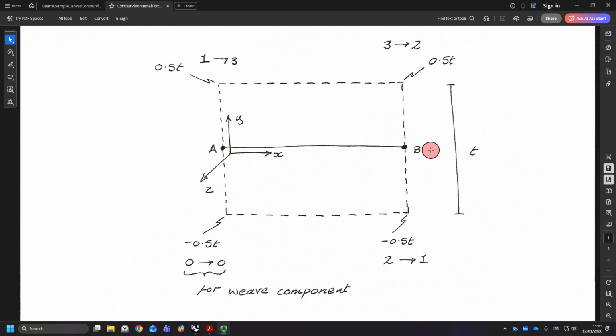And we obviously have the values for the internal forces, so the axial force, shear force, and bending moment at those nodes. And what I want to do is I just want to generate a mesh in Grasshopper. So it's not a mesh that we're using for analysis. It's just for the purpose of displaying the contour plots.